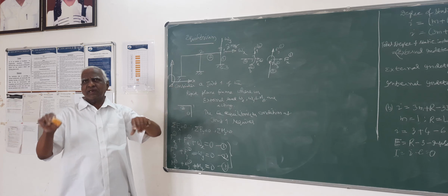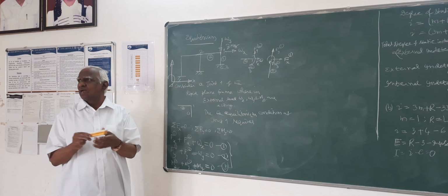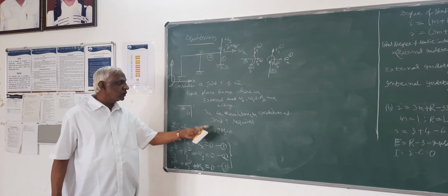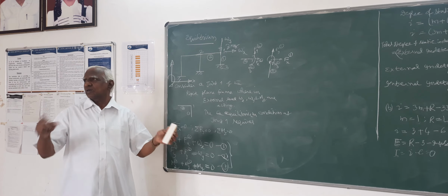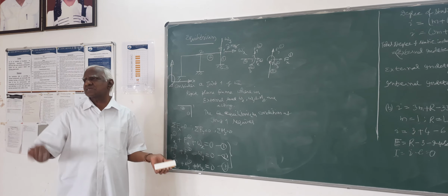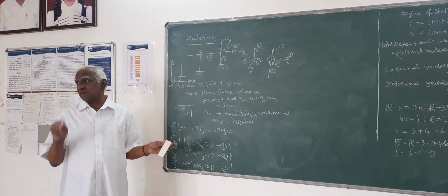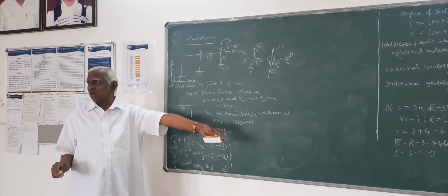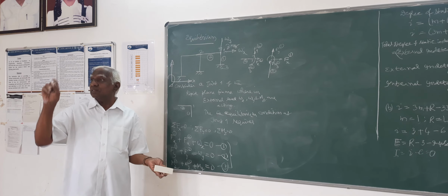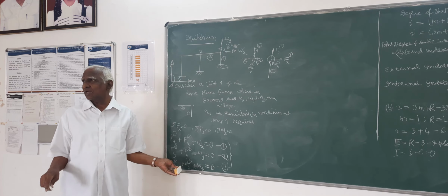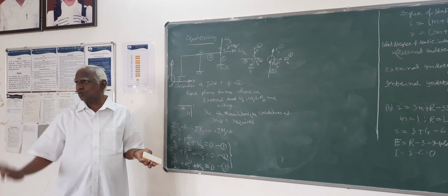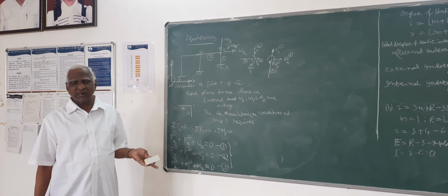Likewise, we can consider a general joint of a truss. At that point also, in a truss you have only one axial force, no shear, no moment. So you can just take the algebraic sum and say that is what applies at each joint. That's why we are determining the degree of static indeterminacy. I consider 3 forces each, like this. In trusses only 2, you don't have to consider moment, and that's it.